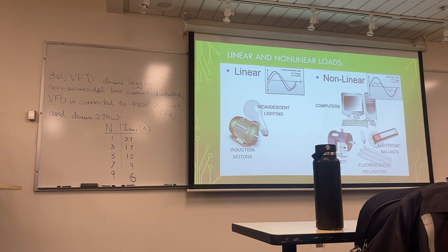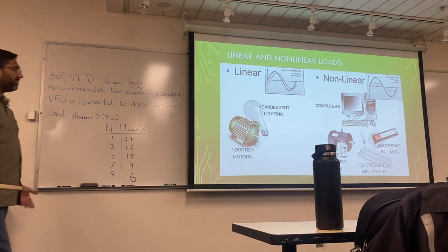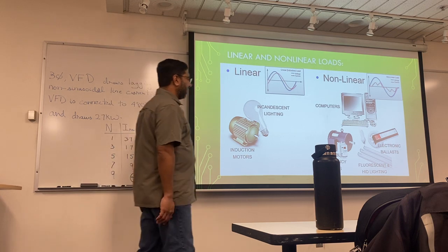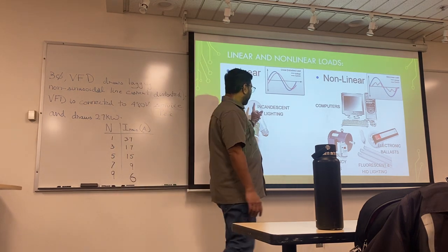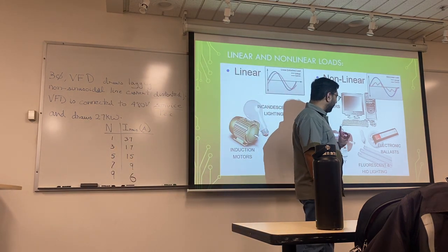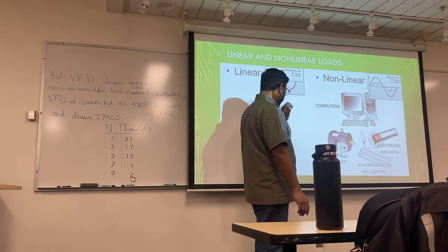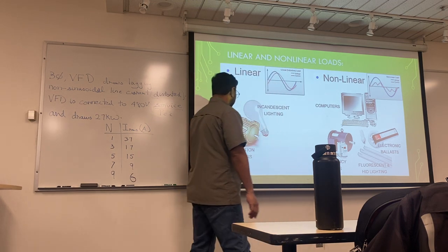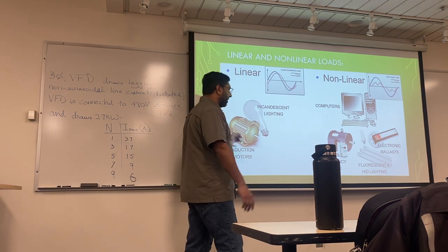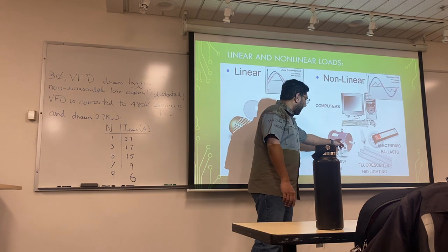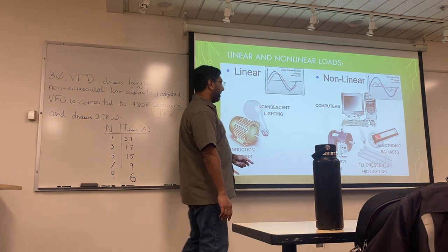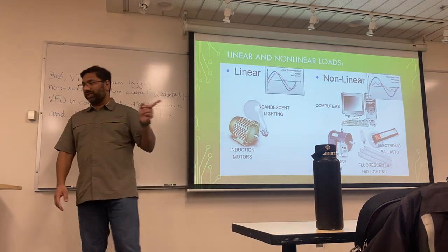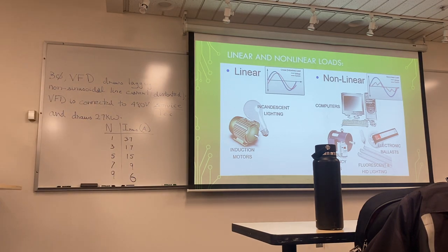So just to give you an idea of what a linear load looks like and what a non-linear one looks like. Just because it's a lighting device doesn't mean it has to be linear or non-linear; it depends on the device. Similarly for motors, if you have just an induction motor, it's a sort of linear load. The moment you have a drive introduced, it's a non-linear load. Again, that's part of 348 and your machines class, which is a 500 level class. But it gives you a great visualization of what I'm talking about, a linear and a non-linear.